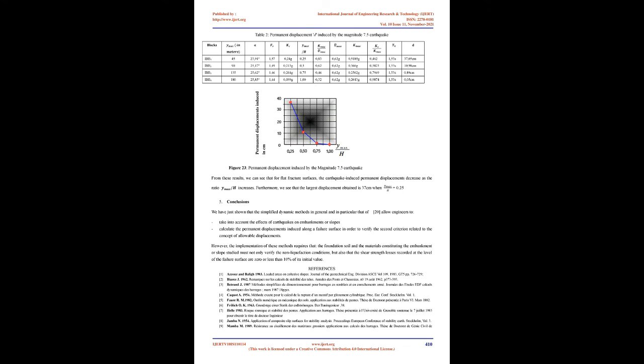The values of the shear modulus G equals 216 MPa and the density equals 2 T/m3 allow us to calculate the natural periods of the different modes of vibration of the dam, which are given in Table 1. The application of the flowchart in figure 21 requires the calculation of the ratio, which equals 0.36. This allows us to use the curve in figure 10 to find the value of cyclic distortion equals 0.065%.